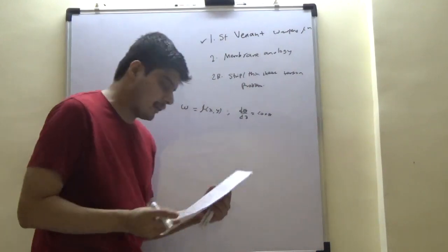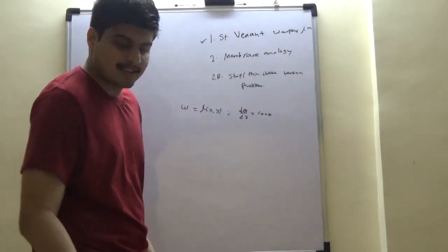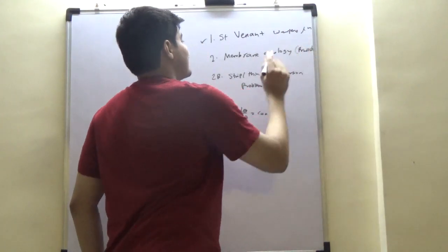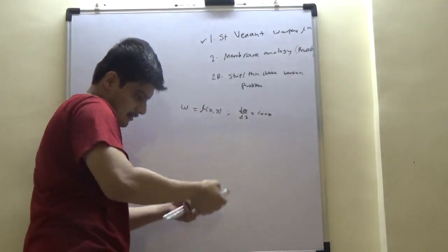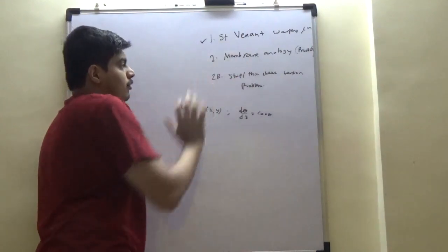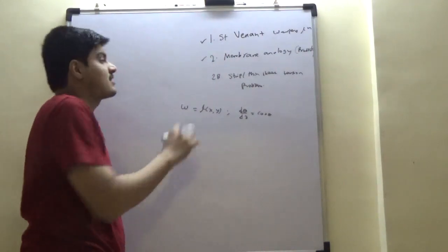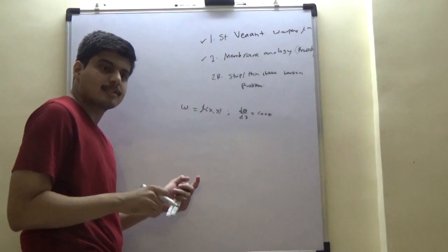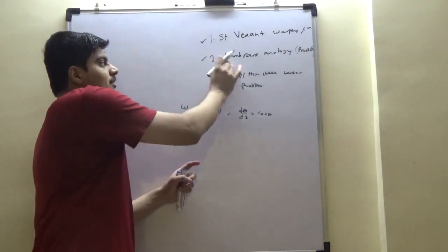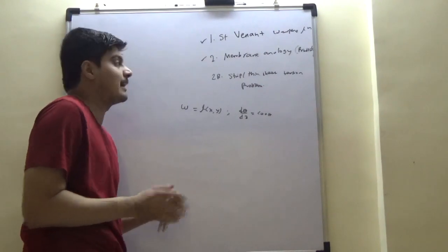Again, this was done by Prandtl, and let us reconfirm that because this is a GATE examination question, right? So Prandtl and his colleague. So it is called Prandtl's, but it is Prandtl and his colleague, right? So it is his analogy that if you look at a membrane which is squeezed and which warps out, twists to resist that load, the problem of torsion and membrane are mathematically or physics-wise equivalent. The phenomena governing is slightly different, but the setup of the problem is such that the analogies are identical, and it simplifies your task to solve these equations in detail.